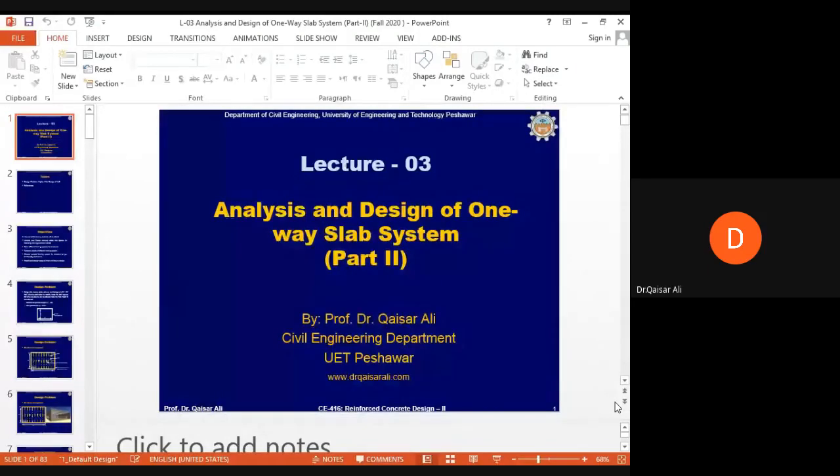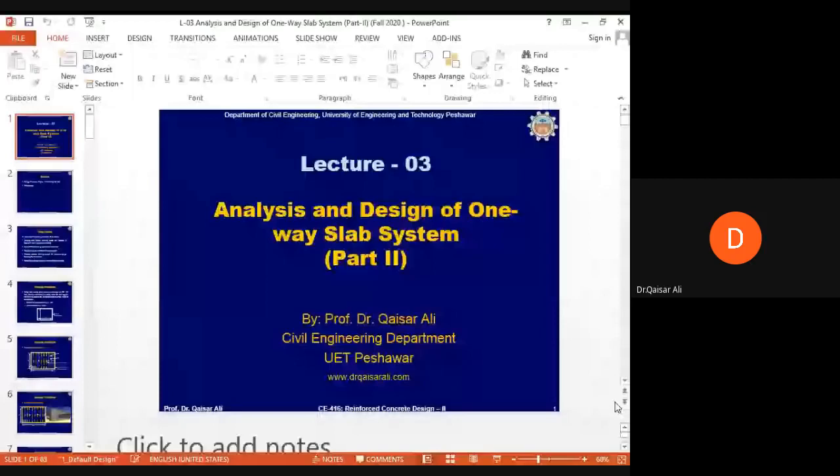And when you saw a support section near the support, what did you see over there? The upper bars became 4 and the main bars became 2, because he turned two of the main bars up by 45 degrees to support the upper bars. And he said that the shear at the support is the maximum, so it needs to be supported.